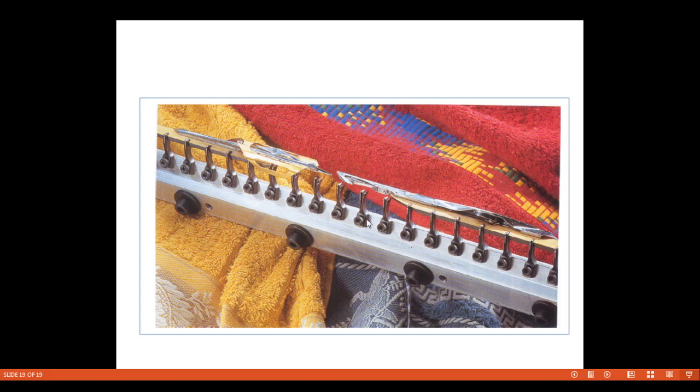On the sley we can see here guides are there. So in the guides the rapier tip is going inside and outside. So this is a guided rapier. You can see a guided rapier, and this is the left hand rapier. So in the design of the rapier we can see this is the giver and taker. So giver and taker design we can see here. At the center they collide with each other. The taker rapier goes inside the giver and grabs the weft at the center and brings it to the right hand side.